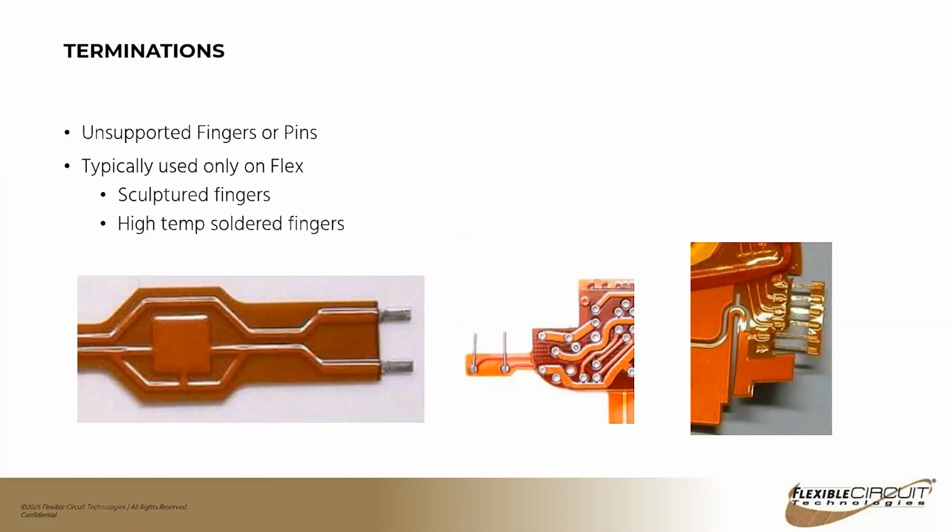Oftentimes, the solder that's used to attach the pin or ribbon to the circuit would be a higher temp or a higher reflow temp than what you're going to make your termination to on the other end. So when you go to solder that pin onto your PCB or device, you're not going to reflow that higher temp solder that connects the pin to the circuit itself.